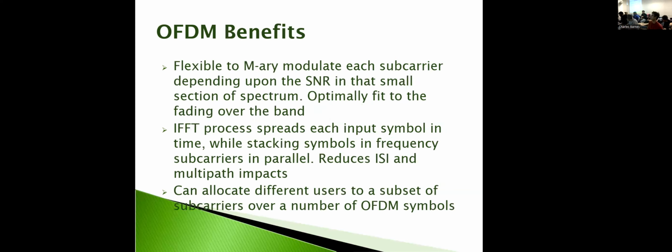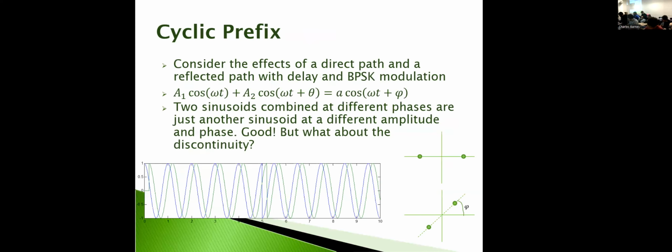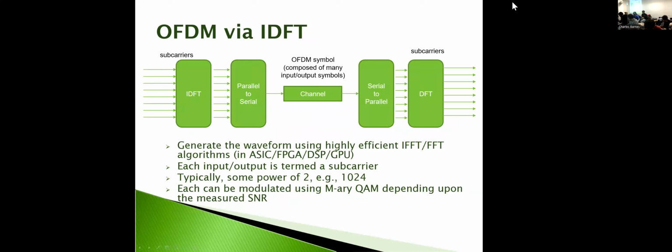If you have a big Doppler shift, then at the receiver the signals are going to be shifted. Instead of lying in this maybe 15 kilohertz, pretty narrow subcarrier, maybe I've got 2-3 kilohertz worth of Doppler shift, and the whole spectrum slides in this area.